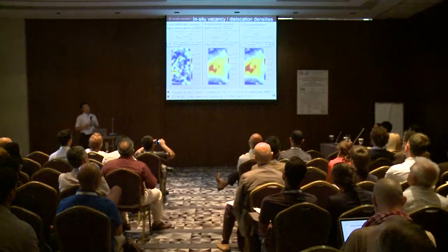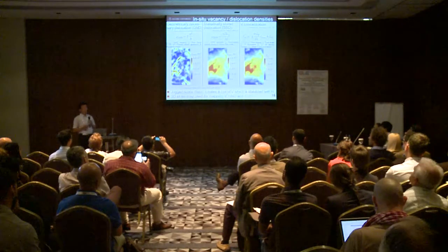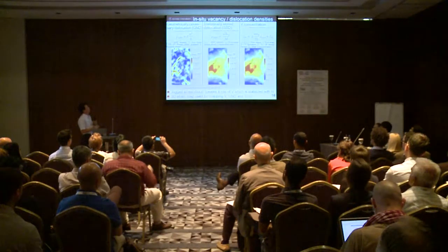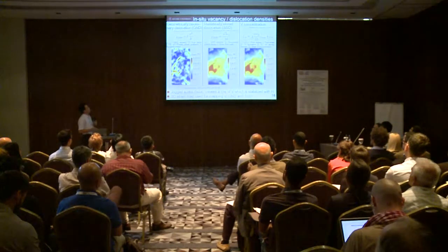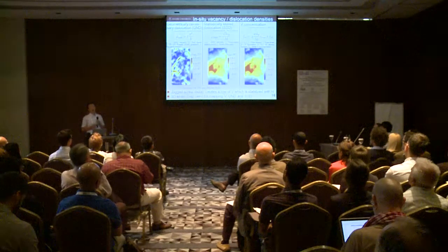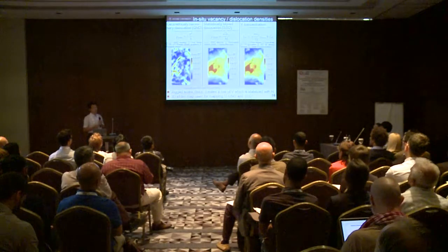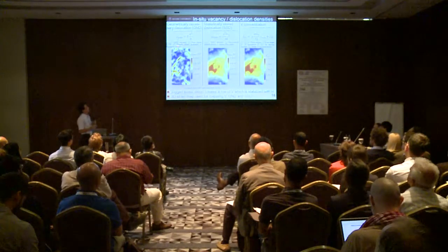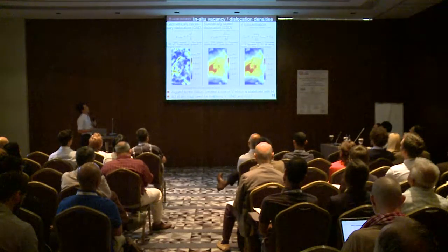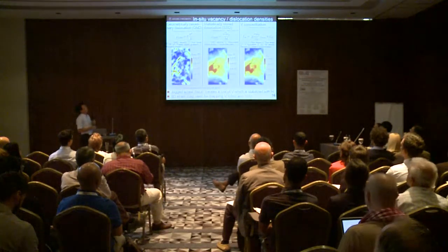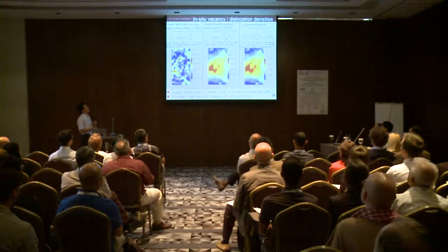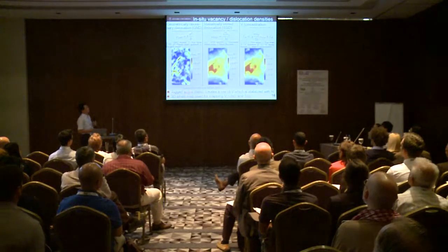And we also need some information about trap site densities. This is geometrically necessary dislocation and statistically stored dislocation. These can be directly measured from the 3D plastic strain distribution by taking a look at plastic strain gradient and equivalent plastic strain respectively. And we can also calculate vacancy concentration by assuming the motion of jogged screw dislocations during